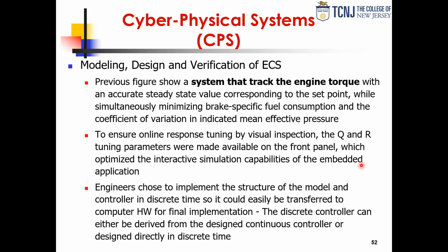At the same time, we want to minimize brake and fuel consumption, because every time you brake, whether it's the user or the cruise control system, then you have to accelerate. So that increases fuel consumption. So you want to minimize that event. And also you want to minimize the coefficient of variation of the pressure that you are exerting on the powertrain.